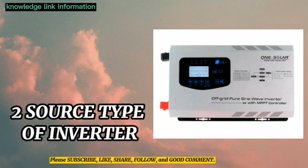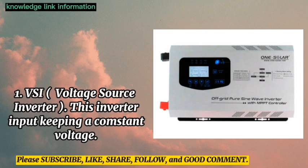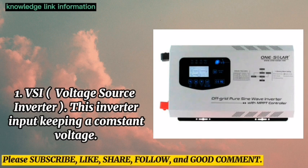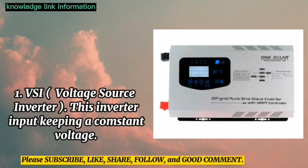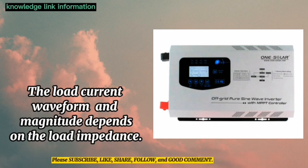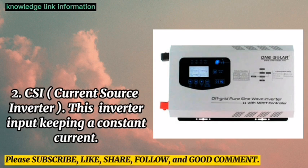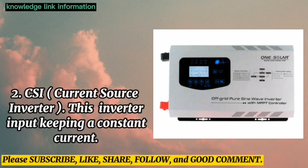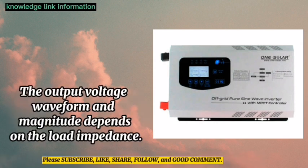Two source types of inverter. Number 1. VSI, voltage source inverter. This inverter's input keeps a constant voltage, and the load current waveform and magnitude depend on the load impedance. Number 2. CSI, current source inverter. This inverter's input keeps a constant current, and the output voltage waveform and magnitude depend on the load impedance.